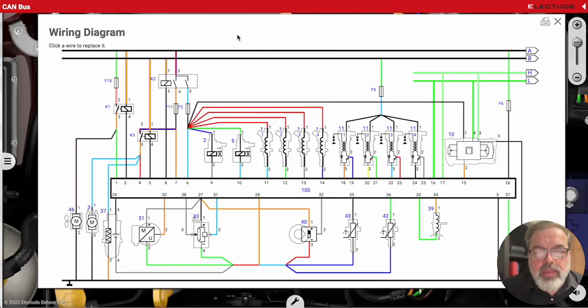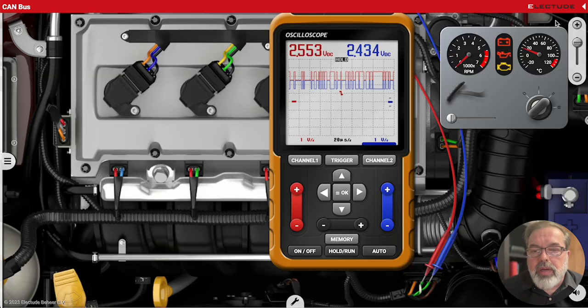So okay, if we get the wiring diagram out, we were getting a signal here. That means somewhere between terminal 3 and 17 we have an open circuit. So what we're going to do is just simply replace this wire on the wiring diagram here. So we just strung a new wire on the car. We could say that we found the open circuit there in the harness somewhere. And now we need to verify our repair. Of course, if the engine starts, we'll know that we've done some good.